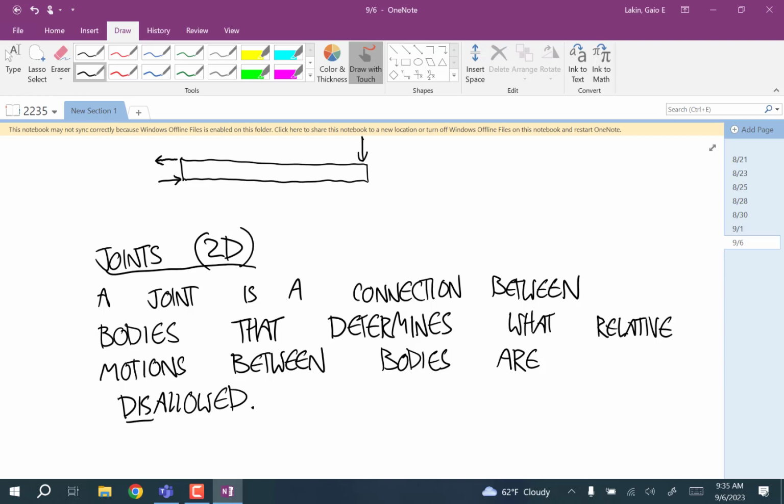In dynamics, by the way, if this body has this one point that's fixed in space, your about point could be the center of mass, or it could be that point that's fixed in space. But since in the end, this is going to have other things that keep it in static equilibrium, we could choose the about point here, or here, or here, or whatever, and get the same answer.